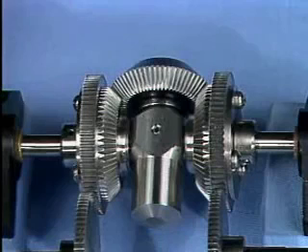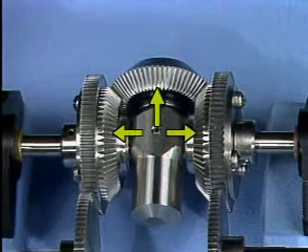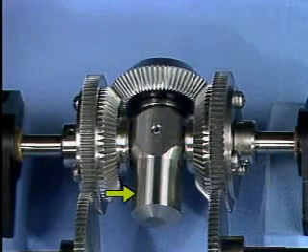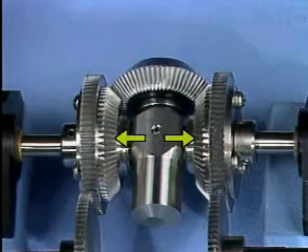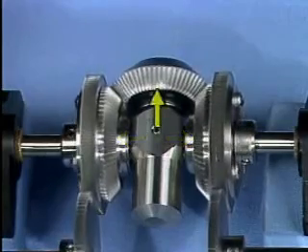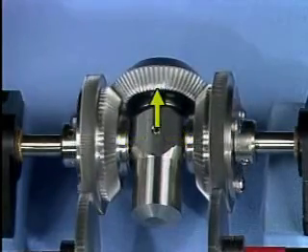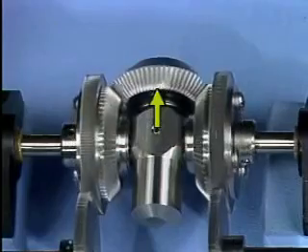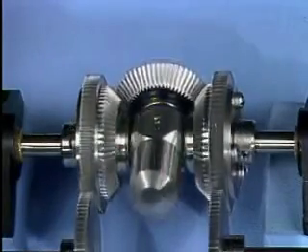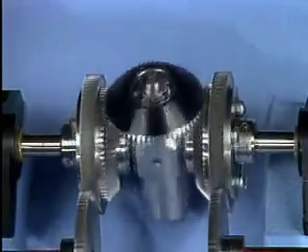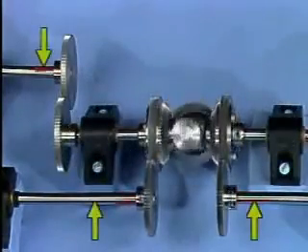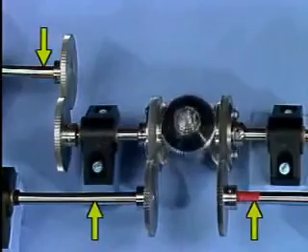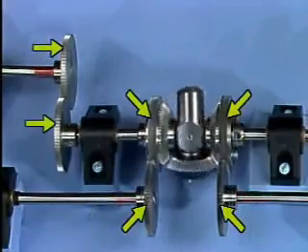This mechanical differential consists of 3 bevel gears, a spider shaft, and a balancing block. These 2 bevel gears are mounted on bearings on the spider shaft and are free to rotate around it. This bevel gear is mounted to a balancing block on a bearing and is also free to rotate. The balancing block is attached to the spider shaft and rotates with it. The shafts that provide inputs and outputs are connected to the differential through these spur gears.